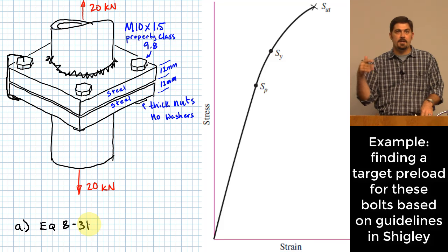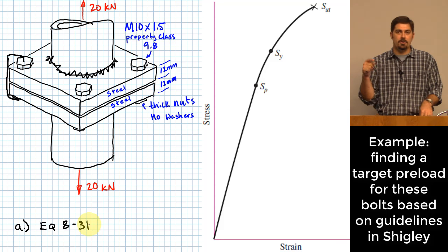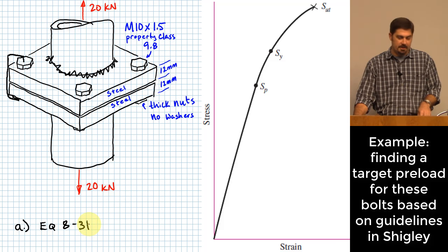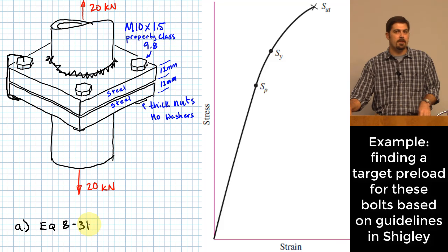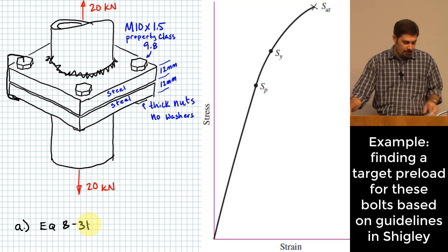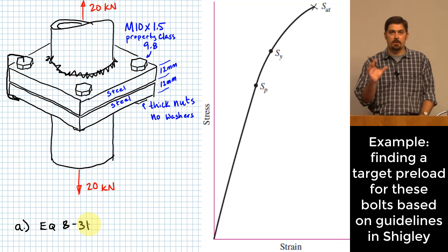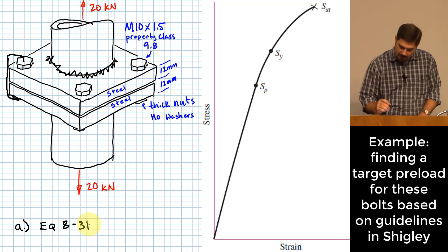The problem is, in materials, you actually get plastic deformation before you can detect it. Okay? And so what they do with a proof strength is they derate the yielding strength a little bit and say, we want to make sure that we're not getting plastic deformation in any part of the material. All right, so these proof strength values are listed in a couple of tables in here for various property classes of bolts. Okay, so that's why the proof strength matters.